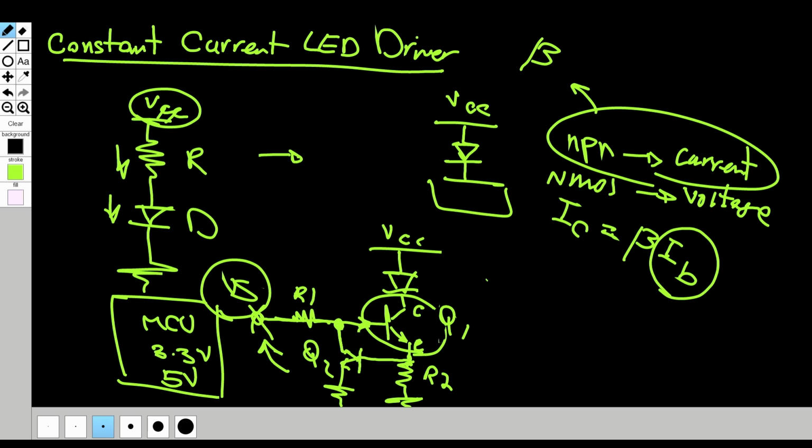So how does this transistor now work, right? Let's go through the same steps. When this VS voltage right here is high, this Q1 transistor will turn on. So the current will start flowing from VCC, goes through the LED, turns on the LED, goes down, and then goes through this R2 resistor, right?